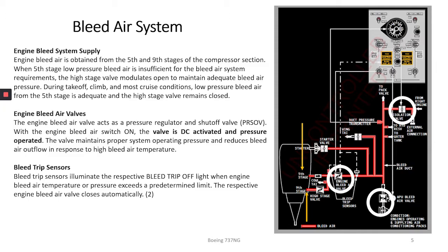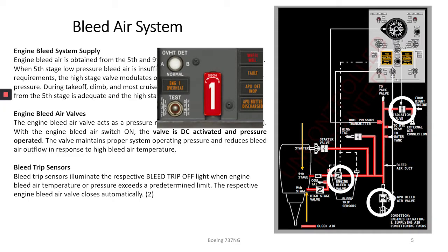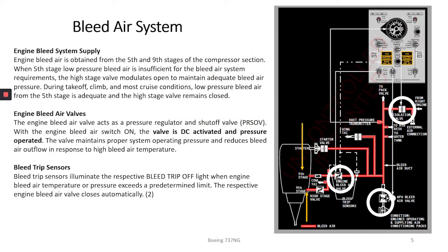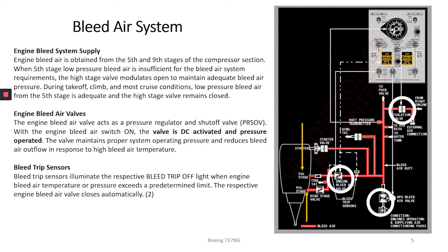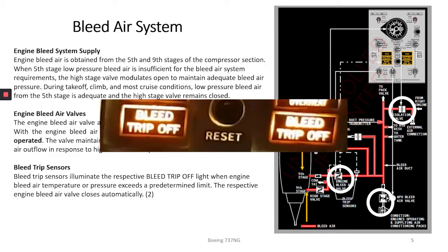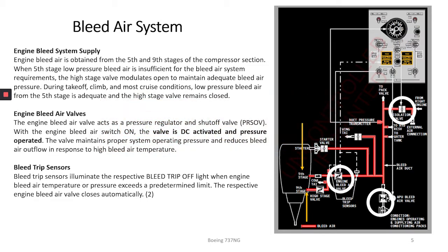There are a few conditions that close this PRSOV: when we pull the fire switch, when the engine bleed air switch is off, and when we have a bleed trip off light, that means an over temperature or over pressure.